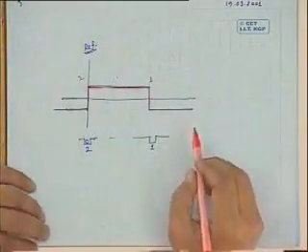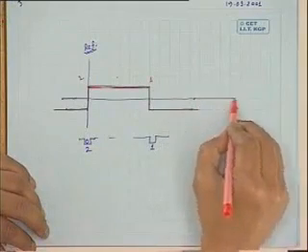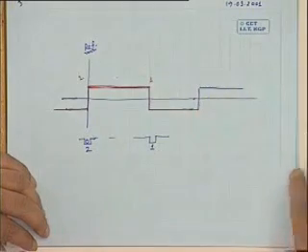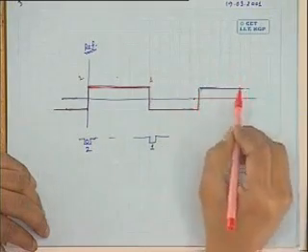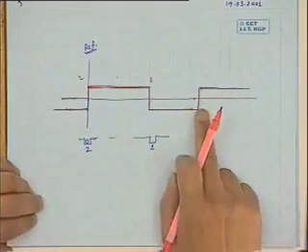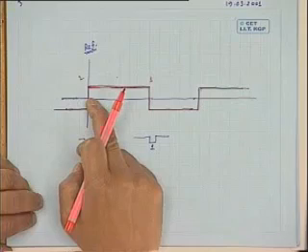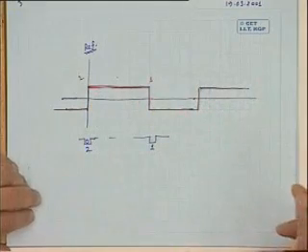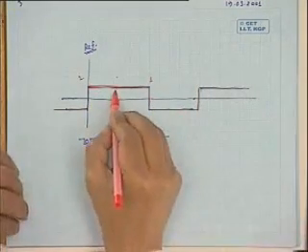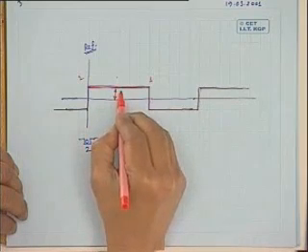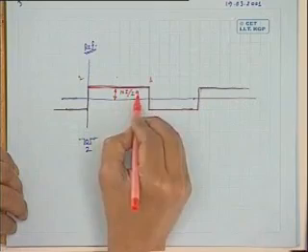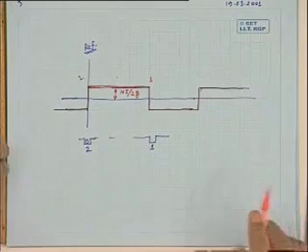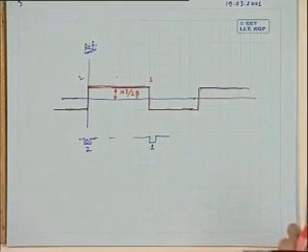So this will be the MMF distribution of a coil, and this will repeat itself because it is a rotating machine. So it will go like this. I mean, after 2 pi, you are coming back here once again. After 0 to 2 pi, you are once again coming back here. So this way it will be represented. What will be the amplitude of this? The amplitude we have just calculated will be Ni by 2G, where G is the air gap of the machine, N is the number of turns, and I is the current. This is the MMF distribution of a single coil.